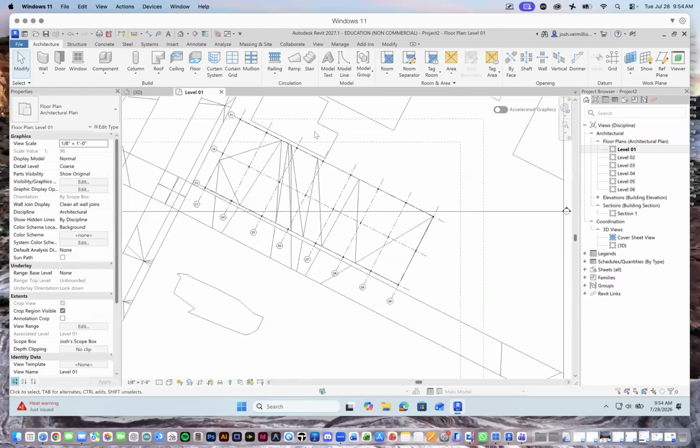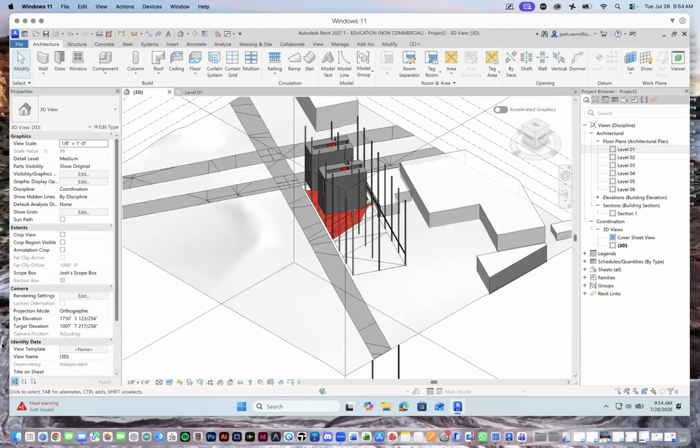What I'm looking at right now is a forest of columns that don't really correspond to anything except maybe the 20-foot spacing. So what I'm going to do is take these lines of columns right here and scoot them back so that they actually line up back here. I'm going to make a spine back behind here, and I'll get rid of this. I don't need these. So let me just try that.